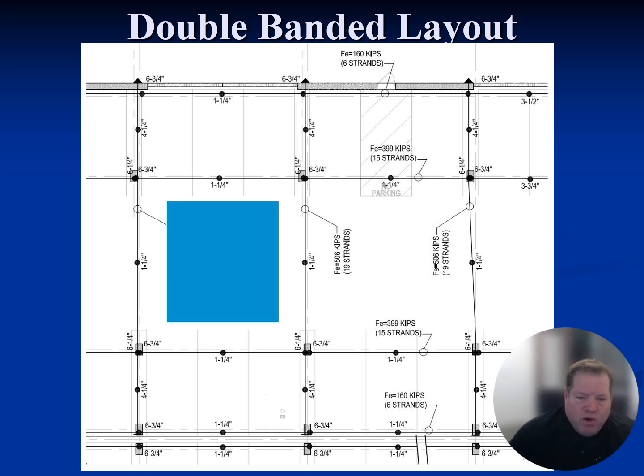So in theory, if you wanted to come in as the owner and just chunk out this blue rectangle, you would be doing it with a fairly certain attitude that you're not going to run into post-tensioning. Yes, you're going to cut some rebar and have those kind of issues, but in general, you're not going to break any strands because there's no strands in this zone. So the demolition, the tenant improvement, stuff like that has the potential of improving.